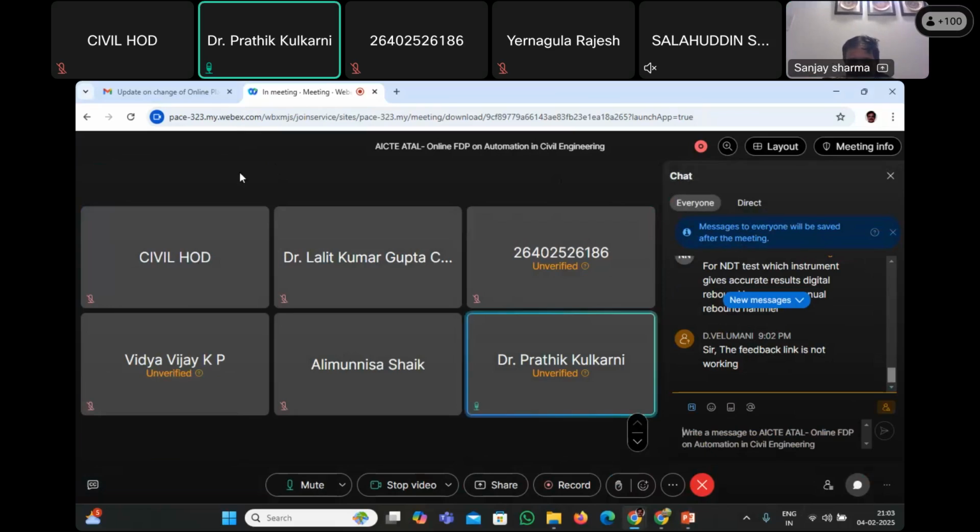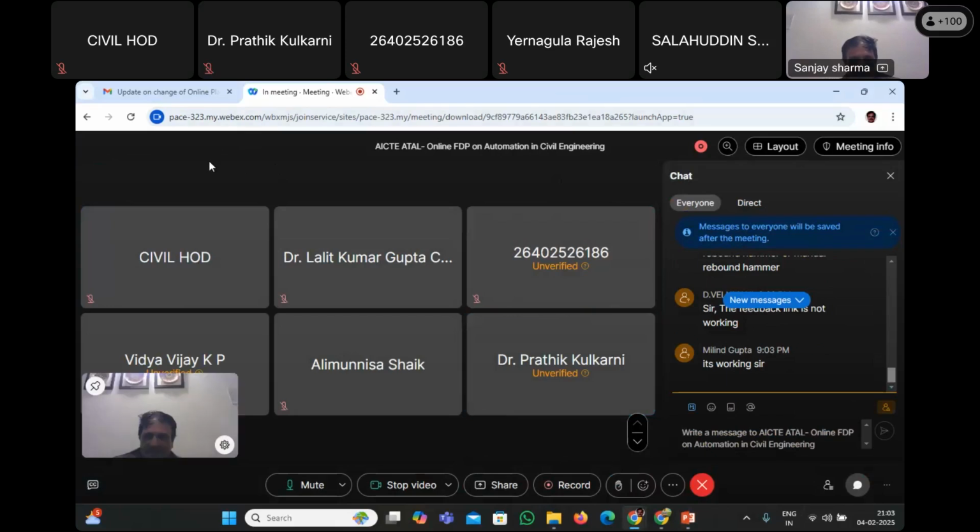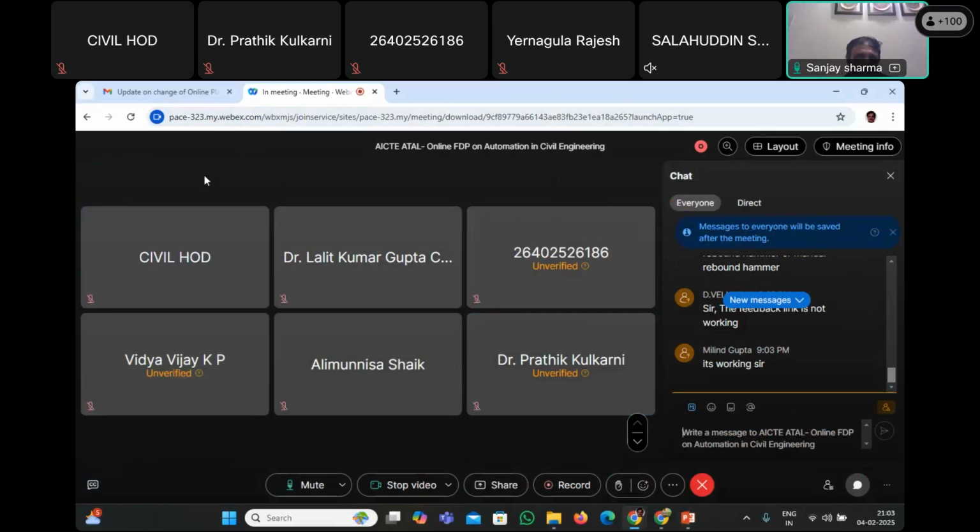But the doubt was, if you go with cement mortar, or even brick masonry, should we have any instrument specific to that? Not in my knowledge, because for stone masonry and brick masonry, you don't have any specific equipment. We have used, no doubt, the P-type rebound hammer, but that may not be there.